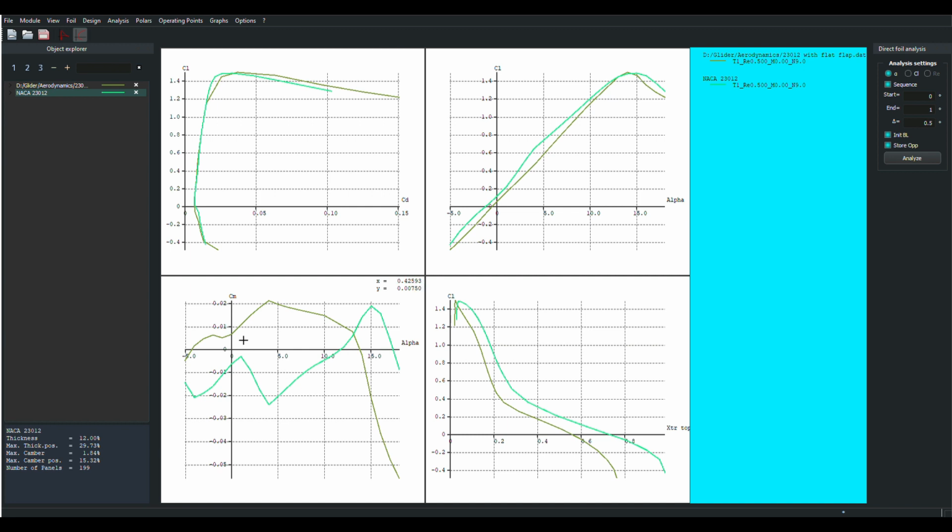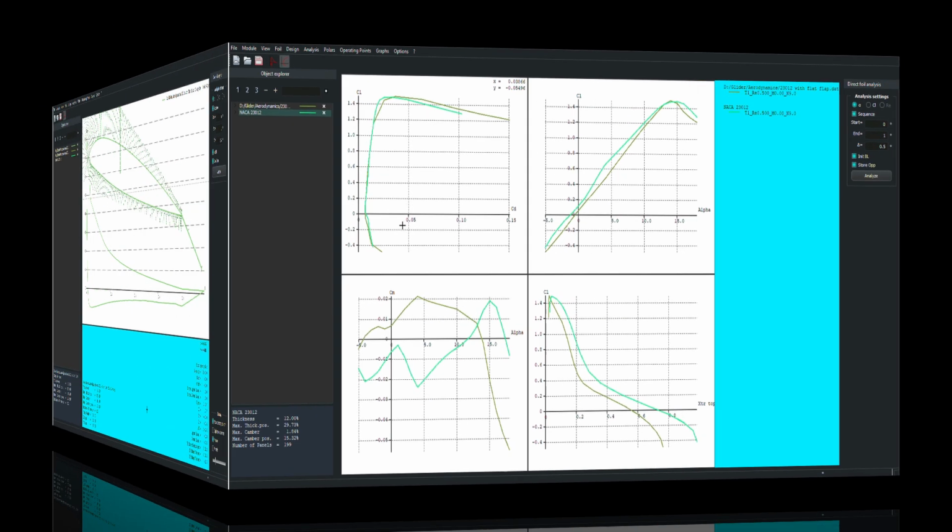I mean, if I put a regular cambered airfoil in here, this pitching moment curve would be way up here off of this particular chart. You'd have a big nose down pitching moment. You'd need lots of washout. So I haven't completely ruined the pitch characteristics of this airfoil by tacking on that plate on the back.